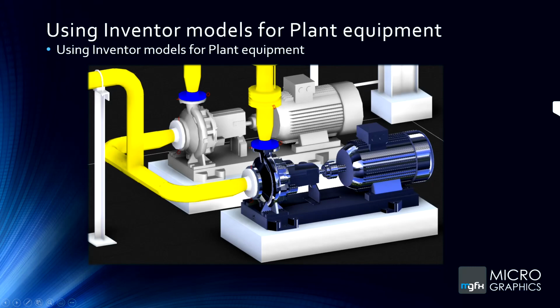And as you can see over here, I actually did it the way that I mentioned. I gave it its proper XYZ coordinate, moved it into position, lined it up nicely, and as you can see, it just gives me a better, higher quality definition to the other plant model that came through originally. Sometimes it's not too clean and you have to kind of get it right, but that is unfortunately a bit of a schlep that you're going to have to face when using it. The good information is you can get a lot more higher quality information from it.